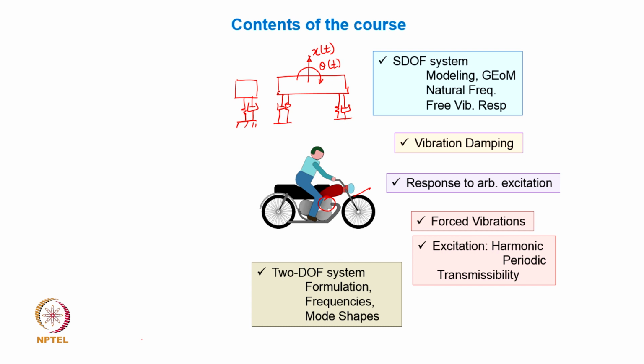So, please make a note that even if the mass is a solitary mass here, the degrees of freedom can be more than one, and we all know that a point mass can have 3 degrees of freedom, that is 3 translationals, and if we account for a mass with a size like a chassis, it will also have 3 rotations. So, associated with it are the 3 inertias, and then you can have 6 degrees of freedom in space, which will be the 6 degrees of freedom of this system. But if you want to limit yourself to a planar vibration or planar dynamics, then x, theta, maybe y if required later, you can have these 3 degrees of freedom for sure for analyzing this motion.